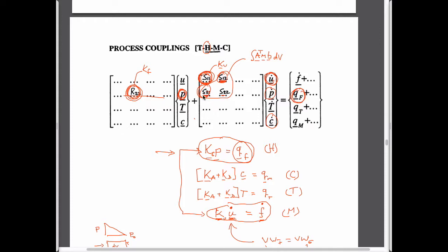And if we want to be able to link pore mechanics in properly, we have to have these two coupling terms. One of these coupling terms acts on displacements and is the volume change that occurs as you strain it and push fluid out. The second one operates on fluid pressure changes and relates to the volume of fluid you have to add to the system. If you increase the pressure, the fluid shrinks, leaves a headspace, and you have to fill up that headspace. So in terms of physical explanation, I think that's kind of what's going on.